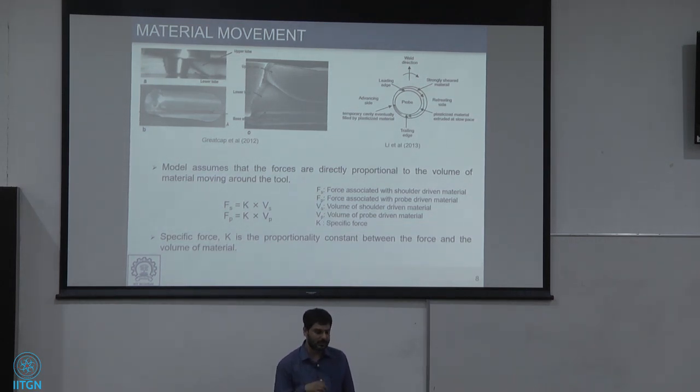However, the material under the effect of the pin moves in a very periodic fashion. And we will see that the experimental work from this project also substantiates this periodicity, where we hypothesize, and eventually the experiments also strongly suggest, that a cavity forms once per revolution behind the tool, and this cavity gets filled by the incoming material moving under the influence of the pin. This cavity opening and filling once per revolution gives a very cyclic nature to the material flow.